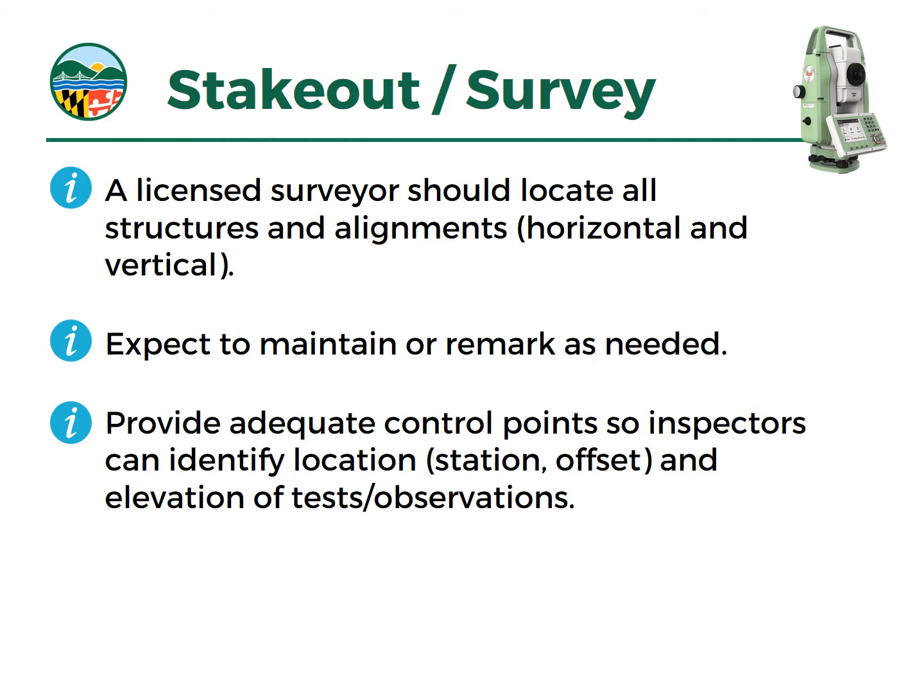Now, a lot of times lately, so many bulldozers have GPS units set on the equipment to help the grading process go more efficiently. So maybe elevation control points are a little bit less critical, because the inspector can ask the dozer operator to set the blade down and wait for a few seconds to get an elevation reading. That's fine, but it's still important to have some kind of ground truth benchmarks out there that can be referred to.